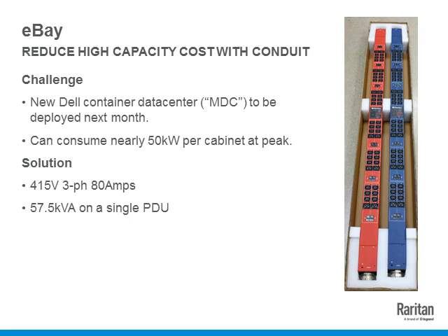And again, this installation did not have any plugs, because you can imagine to get an 80 amps rating, you would need a 100 amps plug, which would have been a significant cost addition to the equation. So we again kept the cost down while providing 57 kVA in one power strip.